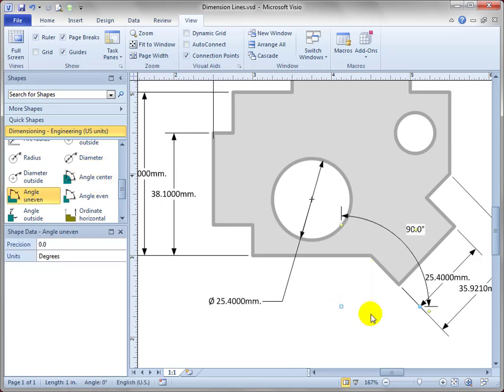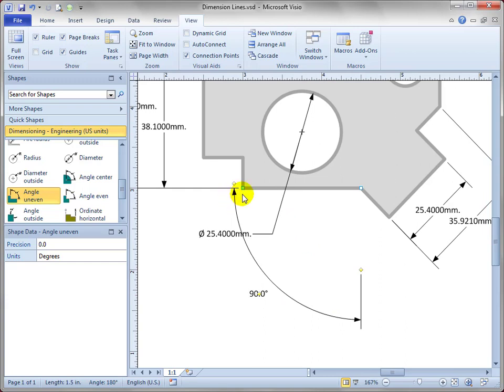Let's start with that. So I'm going to first start with the 1D handles, as I usually do, and I put that at the vertex of the angle. Bring this one over here to another point, and you can see I'm way too far out because I really want to show this angle. Let's see what this handle does. That sets the actual angle.